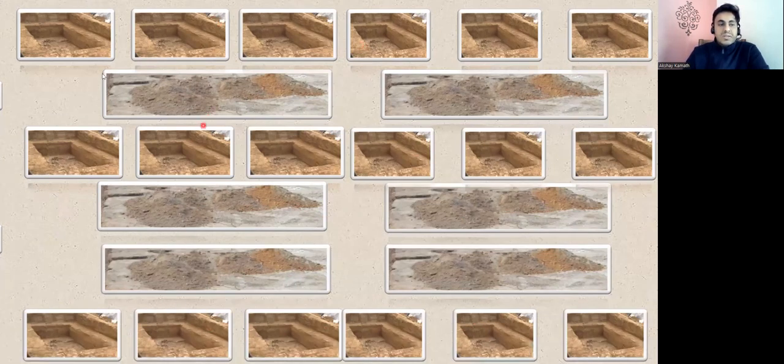Now let us say once you've done the excavation, you want the RMC truck, that is a transit mixer, to come and place the concrete. Let us say on this particular footing here itself, you want to place the concrete. Now, once you call this RMC truck, what will happen? It will come up to here. After that, you already stored the soil here. Now what will happen? This vehicle cannot go from here. Again, here it will be a problem for you to place the concrete.